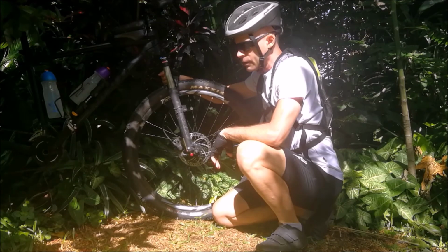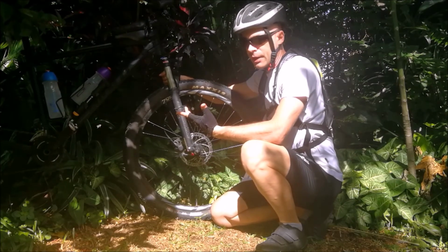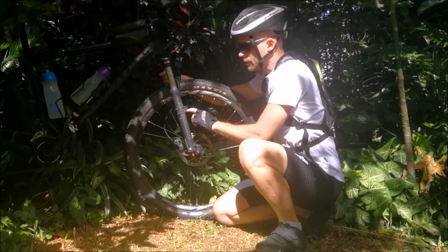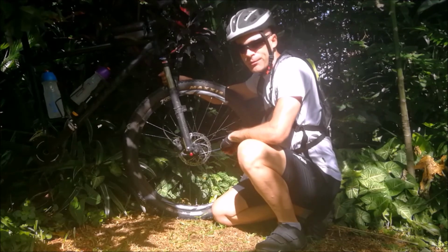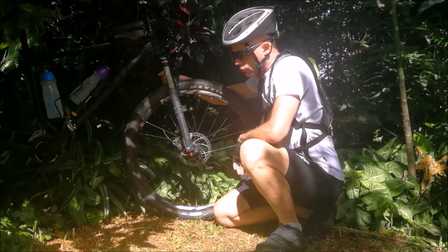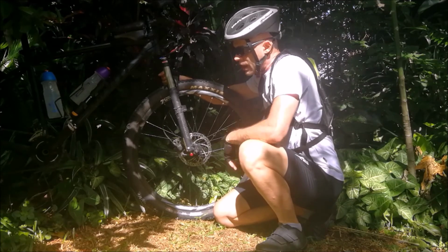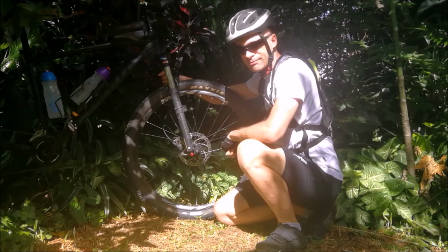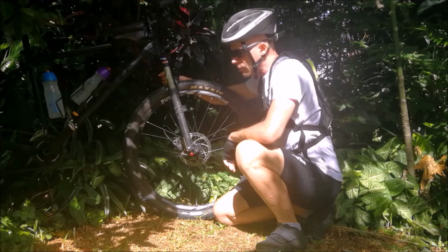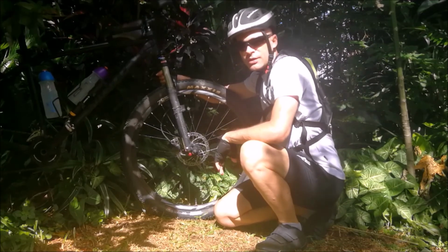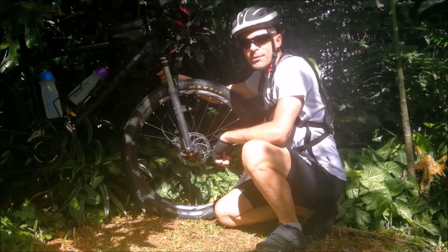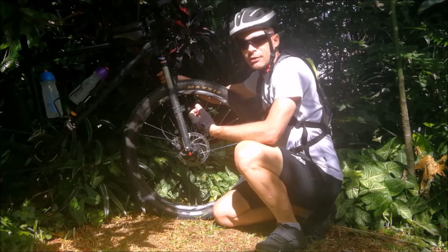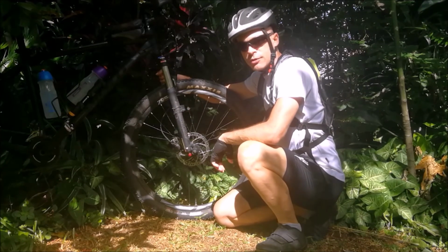So the one issue that could cause errors in our readings is this magnet could be positioned incorrectly, and so the sensor is not able to pick it up every time. Other aspects that can cause error in the readings is that the diameter of the tire could be different to what it's calibrated on the computer system. You could also find that the wheel diameter can change due to things like the tire tread that's worn away. It could also be in terms of the tire that bulges because it might be not inflated as much as it's supposed to be.